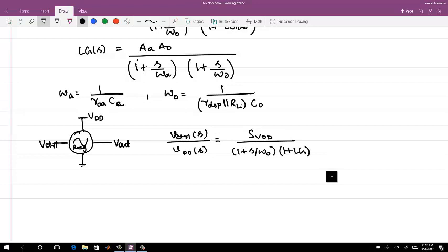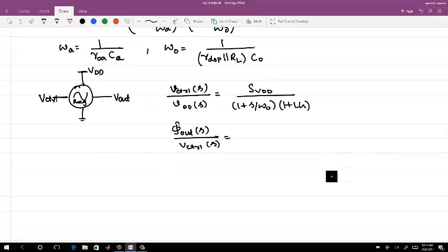Okay, now the transfer function from V control to phi out is 2 pi, or if we are writing kVCO in radians, kVCO over S divided by 1 plus loop gain of PLL. There are two loop gains right now which are here. This is for the regulator.